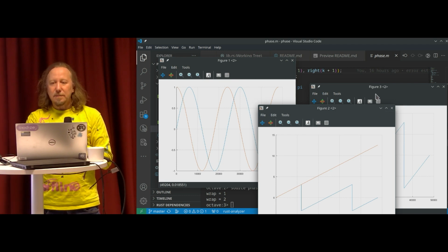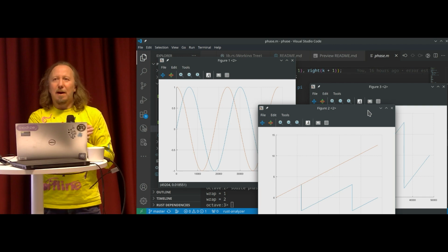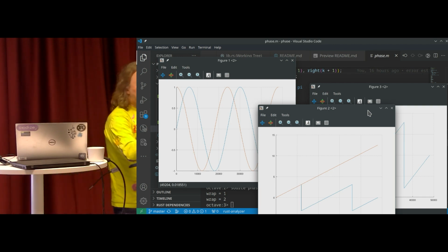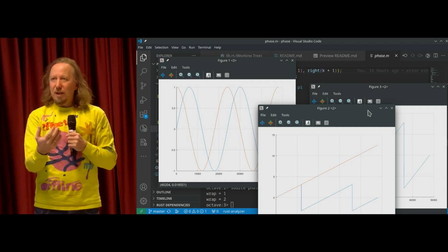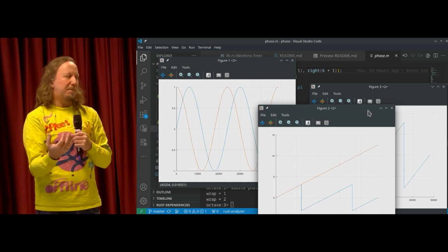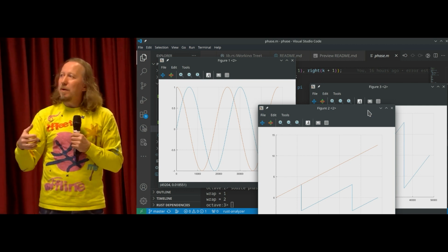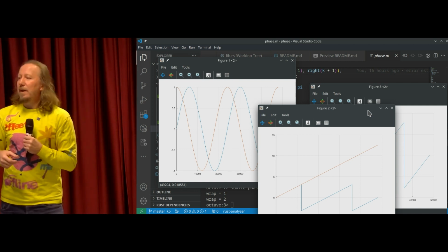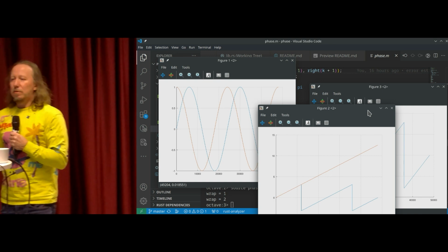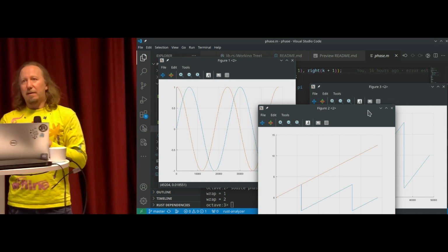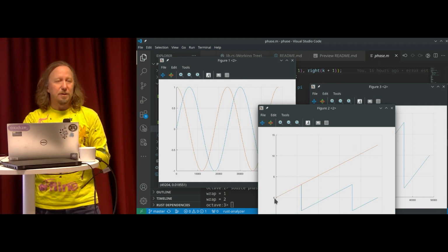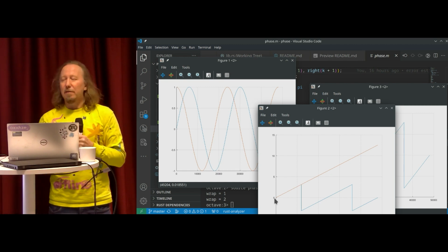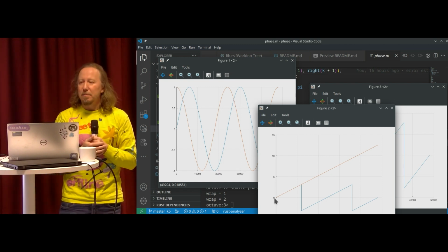Right. So you get the basic idea how this works: on the vinyl we have these two sinus and cosinus signals. We read them through a sound card. We just sample the signals, and we detect the phase of it with an atan2 function, and we unwrap into an absolute position. Well, absolute in relation that we know the start position, but in general it will be a relative position. But the idea is the same.